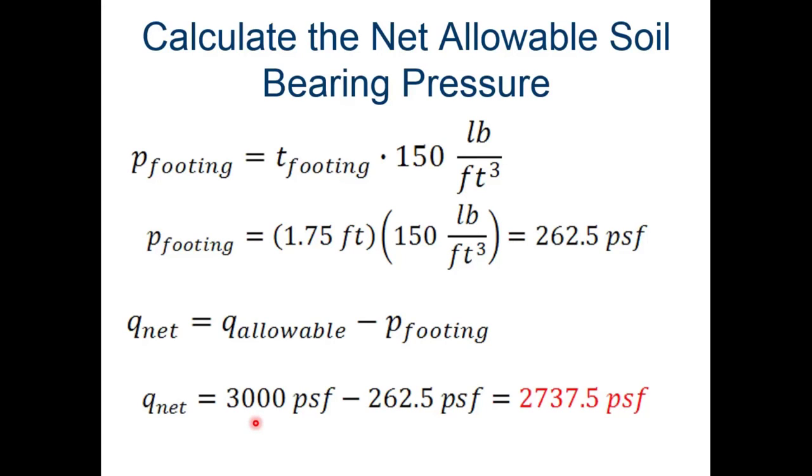If you look on the very last page, my example, when I did my soil testing, I ended up with a, yours might not be red. If you're looking at it on Canvas, it might be red, or if I gave you a color copy, it's red. But regardless, you'll see it's highlighted on the last page. It says sandy soil. Based on our conclusions on the soil testing I did, we ended up with a sandy soil. And that was, if you look across, it says SW, well-graded sand, various sizes of sand in our sample. So that's what we had.